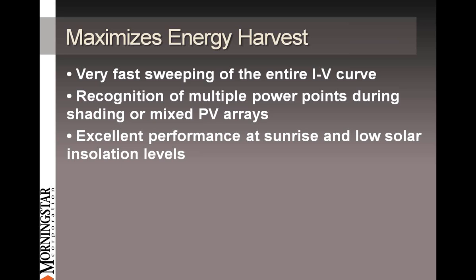We're able to recognize multiple PowerPoints if you have cases of shading or mixed solar arrays, possibly giving you a bumpy IV curve. And definitely there's going to be older modules used with newer ones, different tolerances. The grid-tie market's quite clean and installed, but in off-grid you get a little more original, creative, and sometimes scrappy module selection. So we like to be able to do the best with whatever array is given to us.